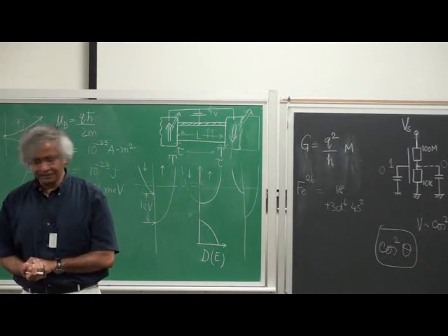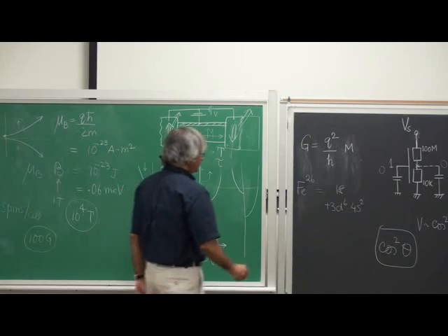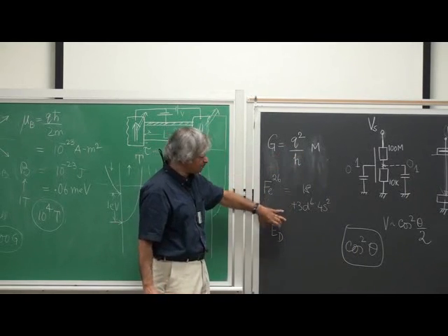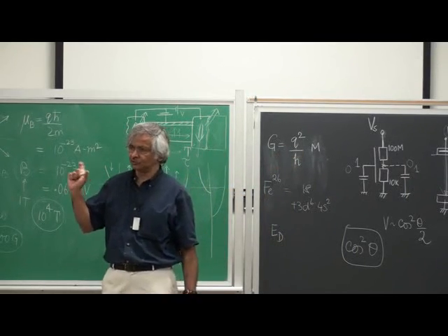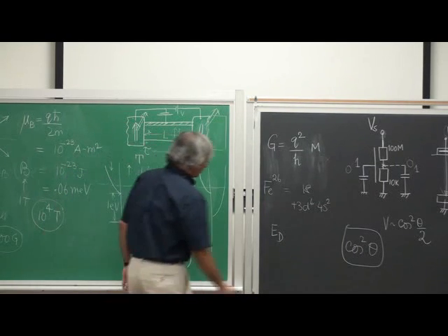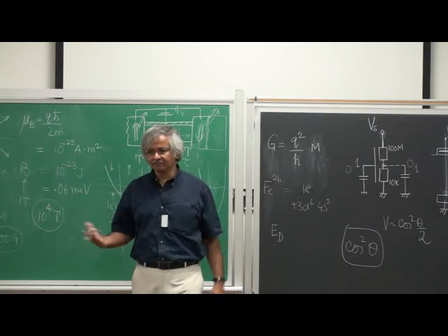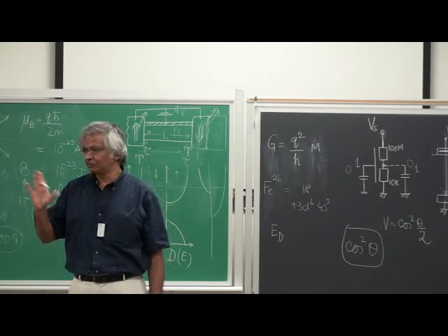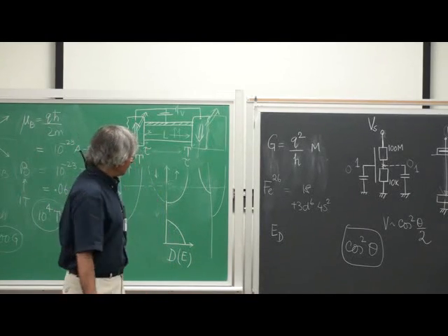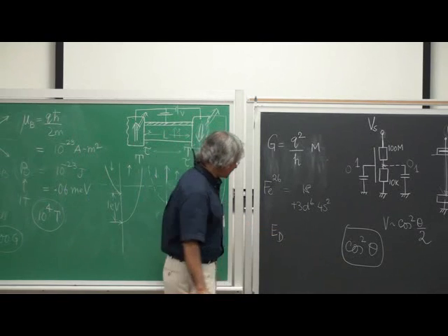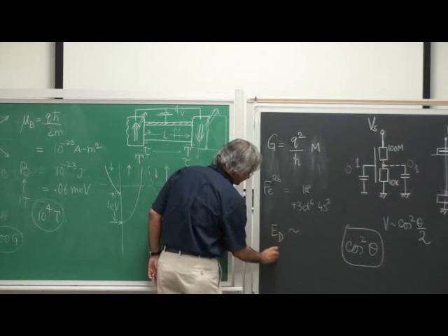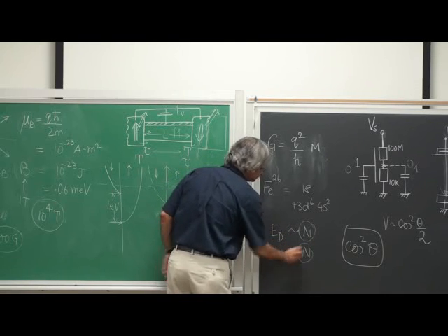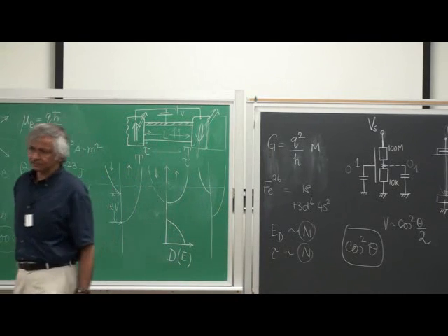And the reason would be something like this: if you look at the dissipation, the energy needed to switch, in the case of CMOS, you'd estimate that for first switch as maybe a femtojoule or so. Whereas in this context, what has been demonstrated, the smallest ones would still be bigger than a femtojoule, let's say somewhere between 1 and 10 femtojoules. Now, could it be smaller? The understanding is that both this and the switching time are proportional to the number of spins involved in the magnet.